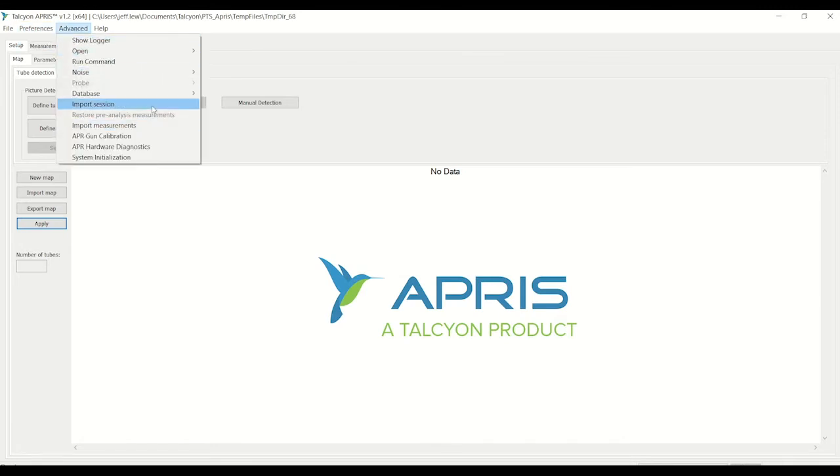In the Advanced menu, we shall use only the APR Calibration and also the System Initialization. We'll use System Initialization when you open up the software first, then you hook up the hardware. The software needs to communicate with the hardware, so this is where you click System Initialization for it to communicate. If you set up the hardware and connect it to your laptop first, and later turn on your software, there's no need for you to perform this step. This step is only required when the software is open first.